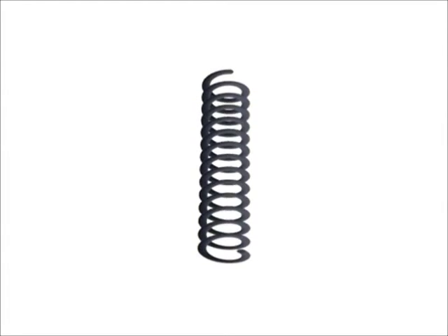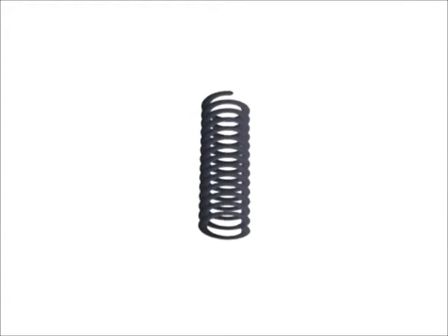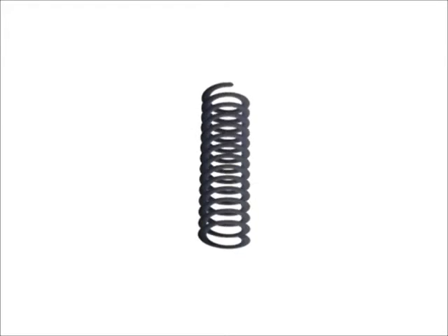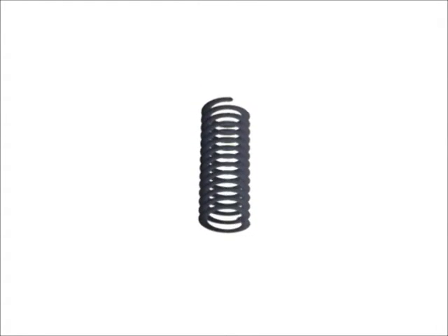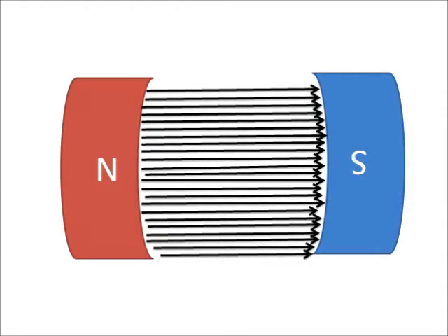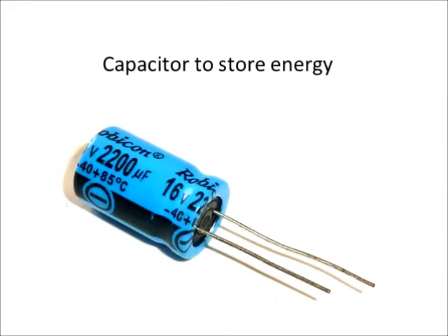We decided to focus on using pressure pads to oscillate a spring within a magnetic field. As the car goes over, the speed bump is compressed, which causes the spring to oscillate. This then cuts magnetic flux between two magnets which we have placed on either side of the spring. This causes an EMF to be induced, which therefore induces a current in the wire which is attached to the spring. This means a charge is present which can be stored in a capacitor